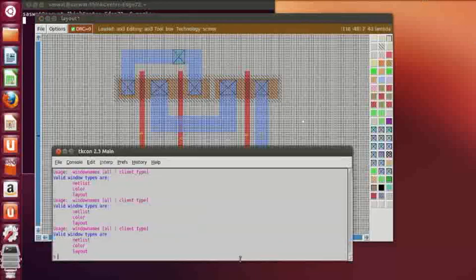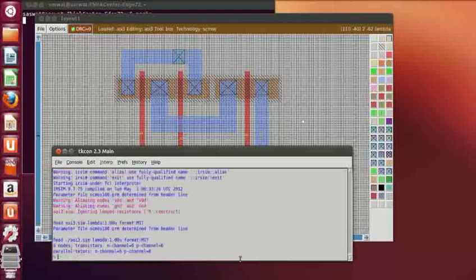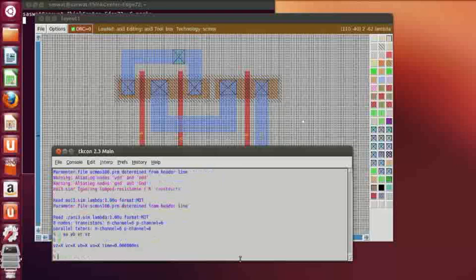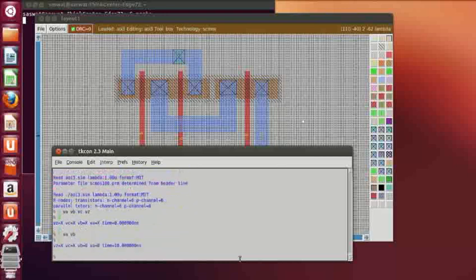Now in order to open the irsim file, we have to type irsim AOI3.sim. Then you want to watch VA, VB, VC and VZ, the inputs and the outputs. Then display, you have the default value. If I give low value to VA and VB, I want to see the output. Since I have not given any value to C, it's showing me X as the output value.